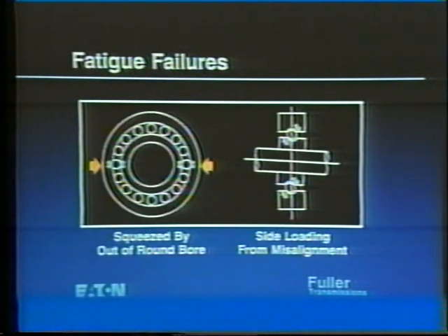Premature fatigue is generally caused by an improper re-sleeving of the transmission case bores in which the bores are machined egg-shaped or off-location. Out-of-round bores will squeeze the bearing races, causing an overload.